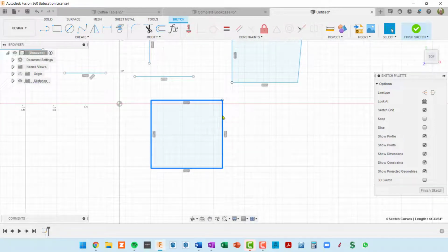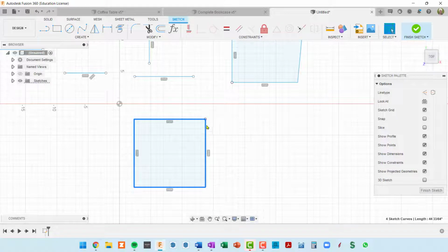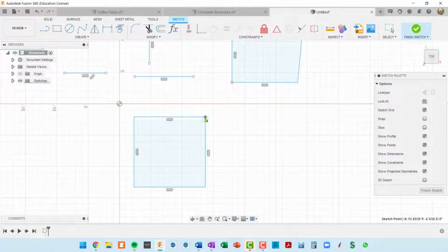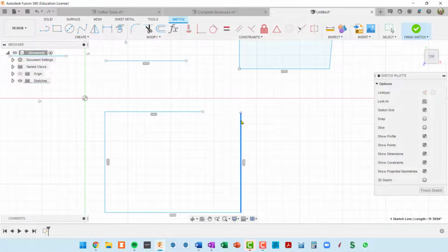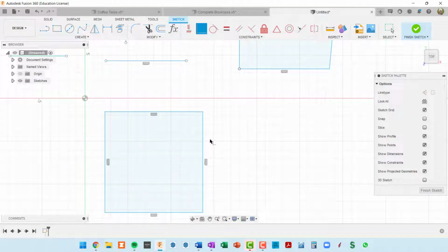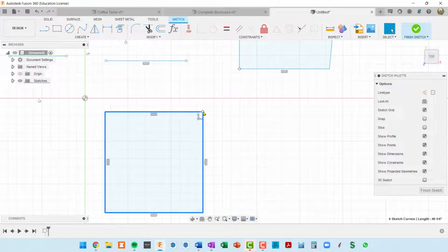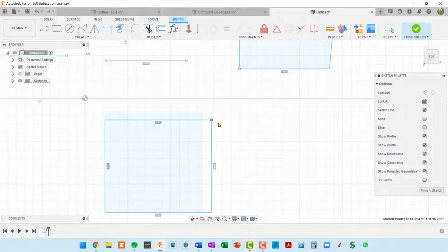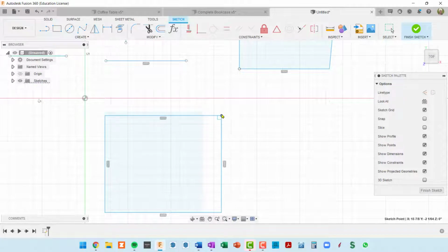Now, since I'm moving this rectangle around, let's see what happens if I take this point. Well, I actually lost my coincidence in the rectangle itself. So first I'm going to kind of heal this rectangle. I'll go up to coincident here. I've got a line selected, so I'll press escape first. Click on coincident constraint. Click on this point, so that should stay put. Click on this point, that moves to it. So now, when I hit escape and select my rectangle again, let's see if I hover over this point. If I drag this point around, the other sides are following, which is what I want.